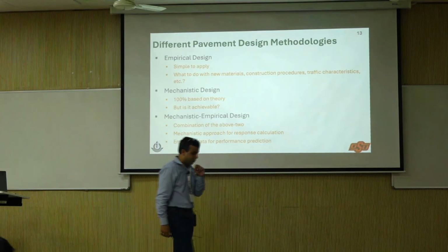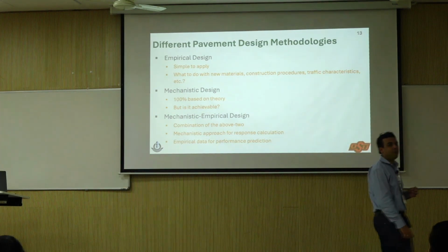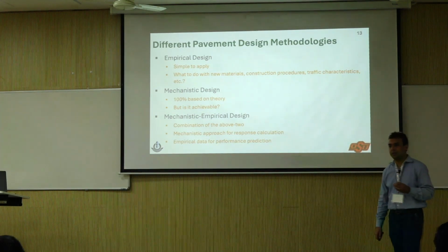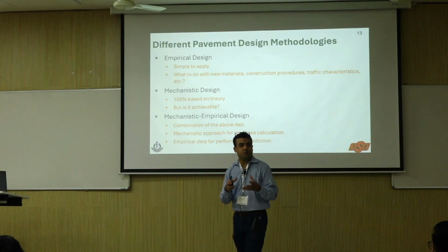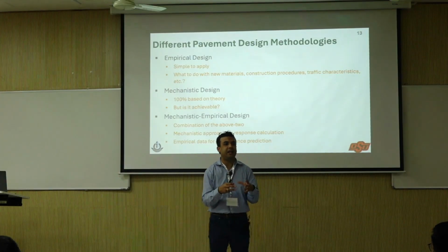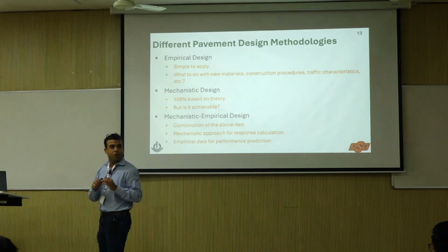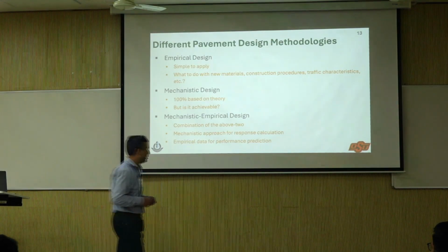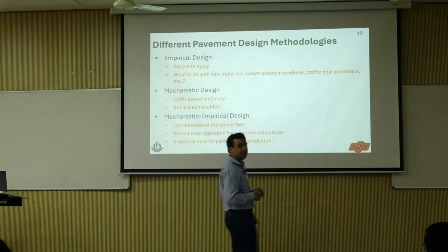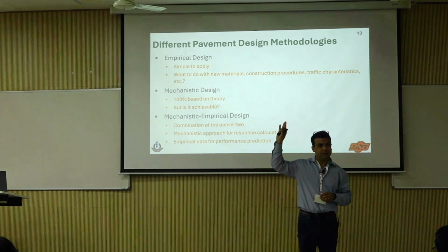Several of you said compaction was something that you are comfortable with. So let's visit compaction a little bit. What is the method used to determine moisture density characteristics in the lab? Proctor testing, right? Proctor was a person, an engineer in California. He developed this. So you have heard of standard Proctor and modified Proctor.